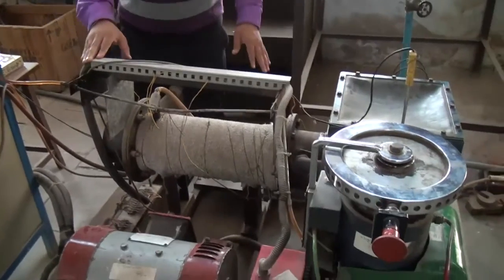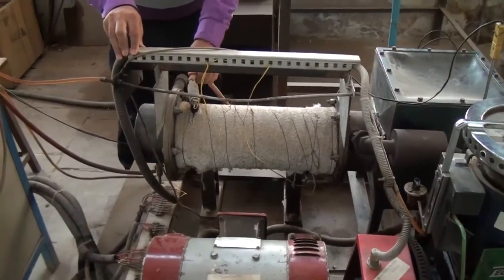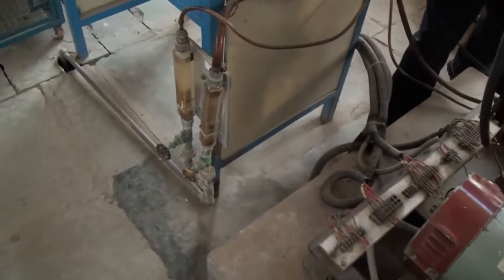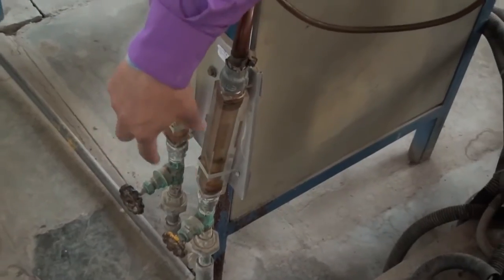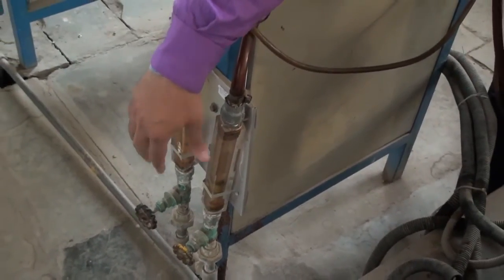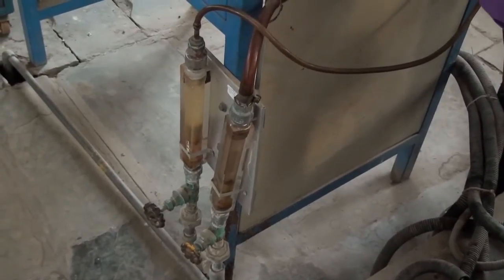Check that the water to the exhaust gas calorimeter is flowing. The water goes to the exhaust gas calorimeter through these knobs and to the engine. Before the start, that should be checked. It should be in open mode, and only then you should start, so that the water starts circulating. So that circuit should be completed.